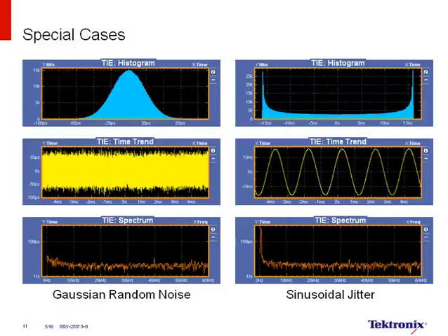On the right, you see a system where the jitter has a strong sinusoidal tone to it. So what you see then is that the jitter will vary in a sinusoidal manner with time. So on the right would be a view you might see if you have a spread spectrum clock that's implemented, or if you have some kind of strong modulation, let's say from a power supply coupling, you will also see that same time trend plot on the middle right.